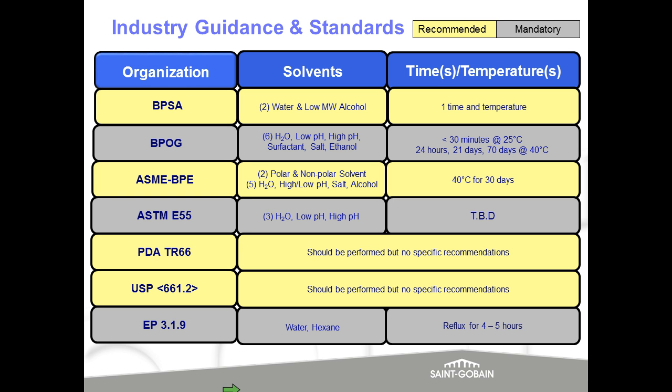If we look at where the industry stands today, there's a number of groups that have recommended and some standards organizations which have mandatory guidelines. BPSA has 2 solvents that they recommend, a water and a low molecular weight alcohol, and then 1 time and temperature. BPOG has 6 solvents that they mandate: water, a low and high pH, a surfactant, a salt, and an ethanol.